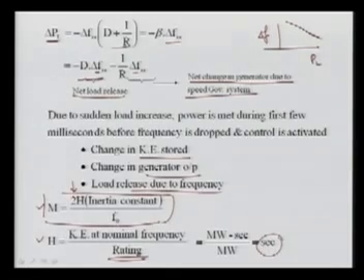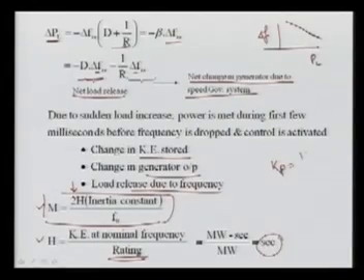Your Kp is independent of this M, always you must remember, because here I said this Kp is nothing but 1 over the D that is coming to the power system, that is a gain, that is a load release. And your Tp, no doubt, is dependent upon D as well as the inertia of the system. And if you remember, I said it is M upon D, or you can write in terms of H. Here I can write 2H upon F into D. So these are the things that we have to use and we have to solve the problem.